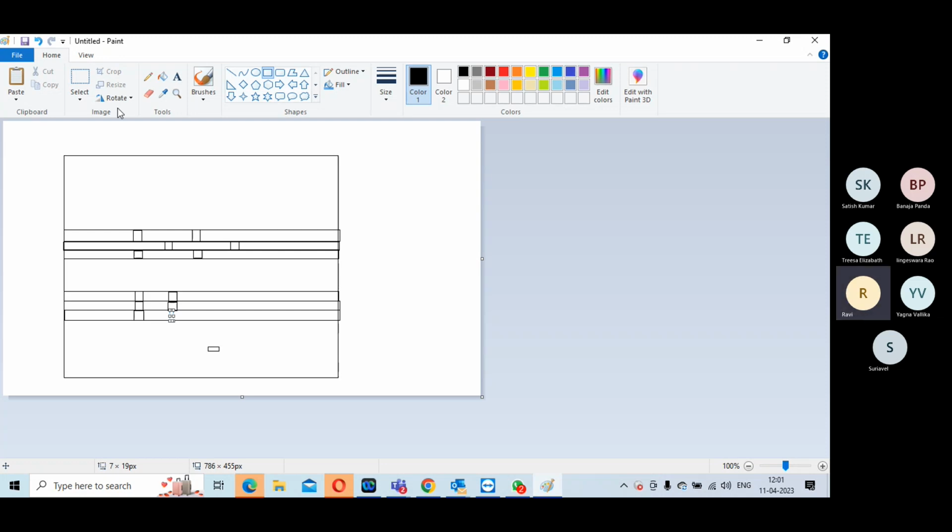ECOable cell, only metal ECO is possible, but you'll have to first switch that to whatever type is needed. If you have made an ECO filler, the cell will have the name ECO fill. Those cells will be mapped to some standard drive logic, because an ECOable cell will have a lesser drive than any of your standard cells.